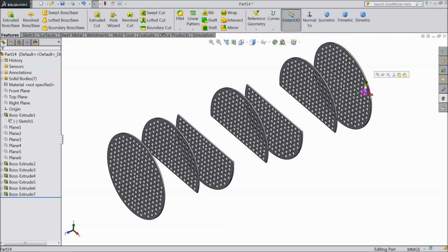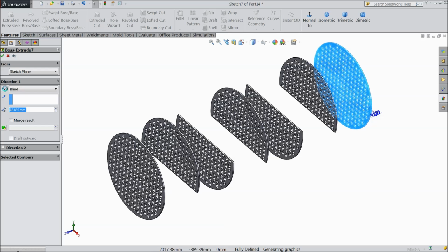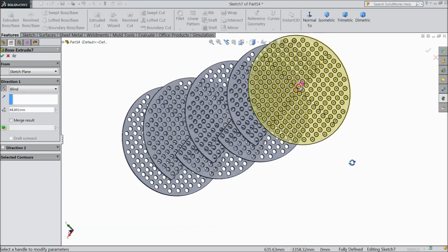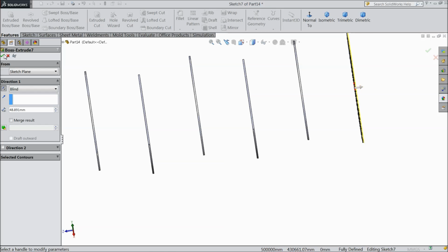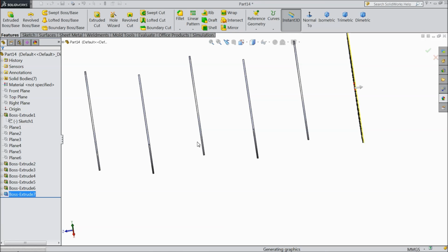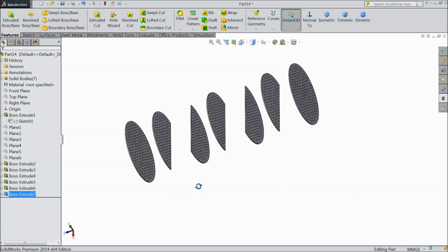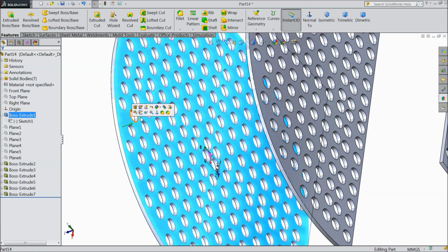Now the heat exchanger tube partitions are created. In the last body we want to do some edit feature. We want to edit something. The extrude thickness should be in reverse direction. So just select reverse. See here, outside. OK. Now select this inside face, sketch.